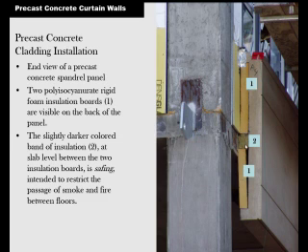And you have to do that between the levels of the floor, because if you're down here on this floor and a fire breaks out, the smoke will travel wherever there's a hole. So you have to seal up between the floors, or any openings, with this fire safing, so that you can confine the fire to the space that it's in, and it reduces the chances of it spreading.